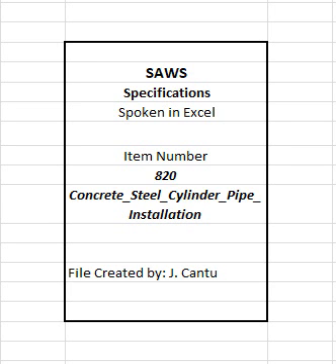5. Do not start production of pipe and fittings prior to review and approval by SAWS engineer. 6. Provide final approved lay schedule. 7. Include hot tapping procedure. A. Tapping of CSC pipe is only allowed by the CSC manufacturer of the pipe brand being tapped or a CSC manufacturer approved by SAWS. 8. Submit certification from manufacturer that design was performed for project in accordance with requirements of this section.